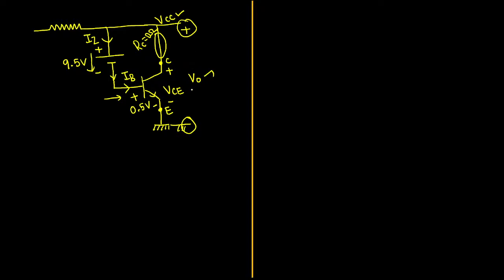So between this we have only one voltage then. VCC, V0, VCE all are same only. Because there is no any other voltage. Emitter resistance also not there, collector resistor also not there. So I can call that the value of V0 is equal to collector to emitter voltage VCE, that is fixed. Next conclusion. I am observing here, that's all.